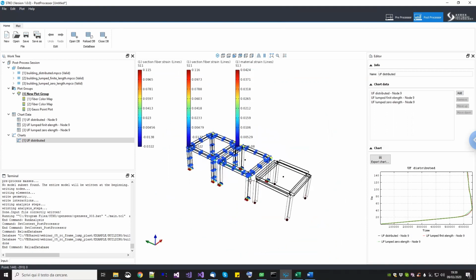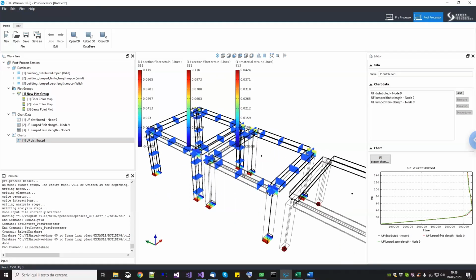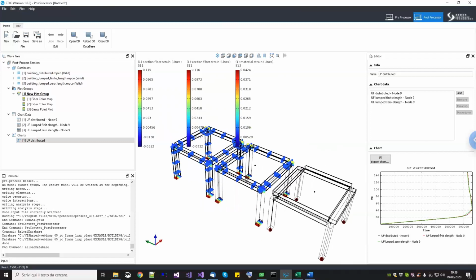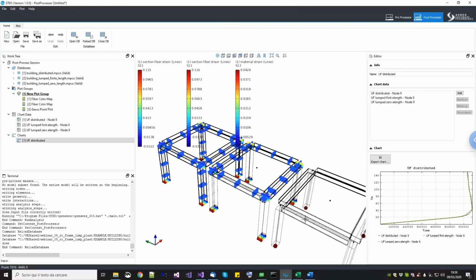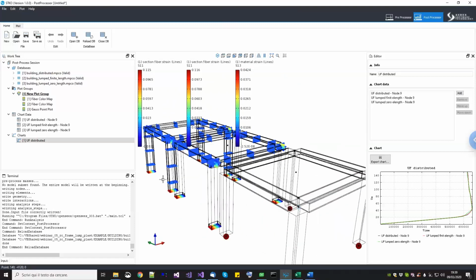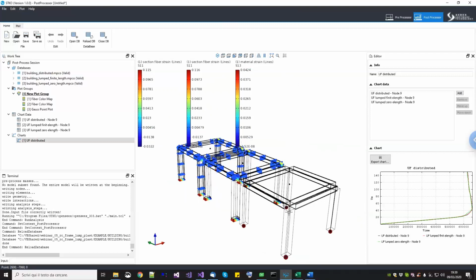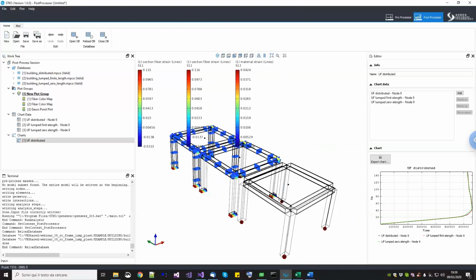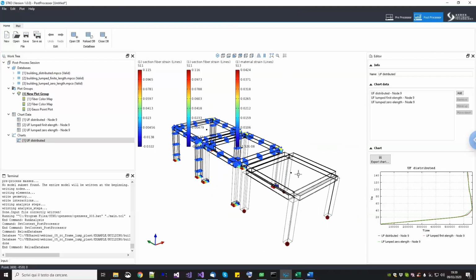Now, of course, we could have done the same for the beams, but I didn't have time. It's already 1 hour and a half now. Well, of course, you can repeat the same steps for the beams. As you've seen, it is very easy. You don't need to replicate the nodes. You can change from one element to the other without changing the geometry. This is the nice thing. So you keep the same geometry and you just change material properties or element properties and you're done. Okay?